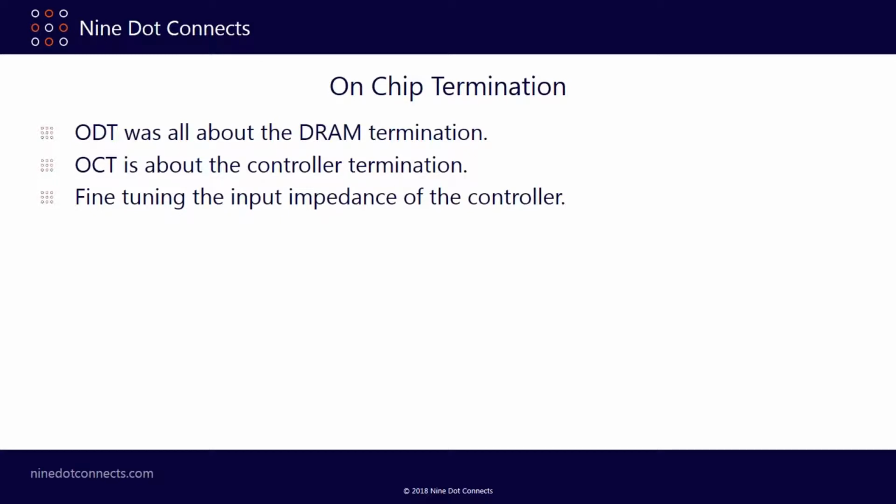Now, we talked on-die termination. Well, that was how we dealt with the memory itself. But when you're talking about the controller, you have something called on-chip termination. It's basically the same thing, but in reverse.